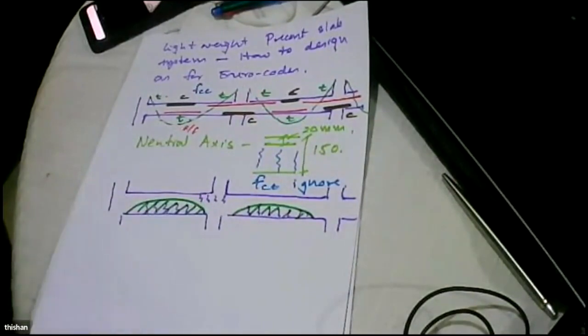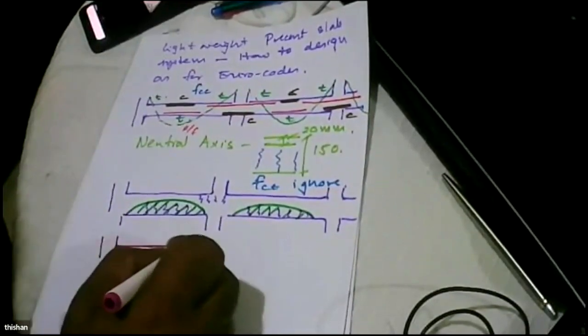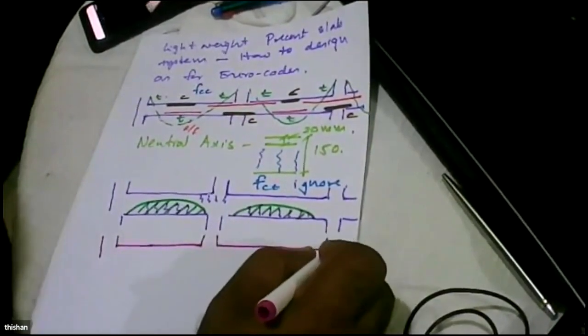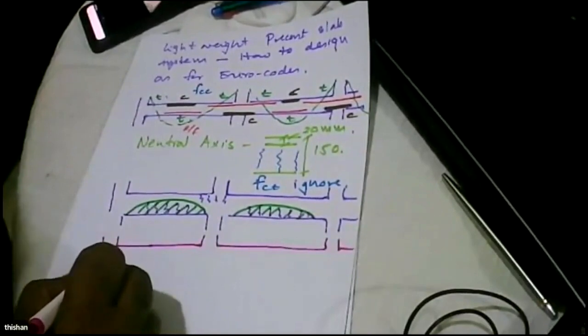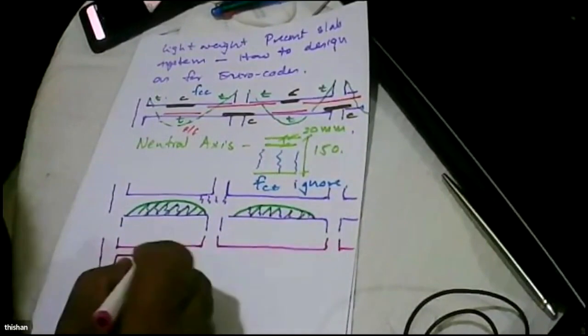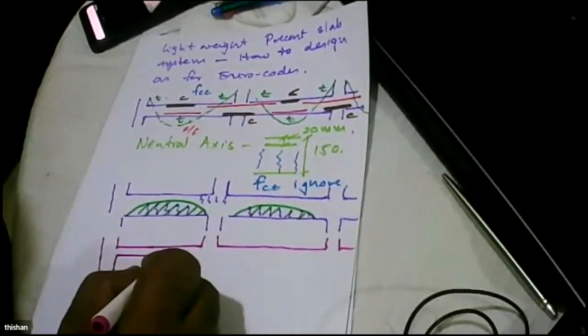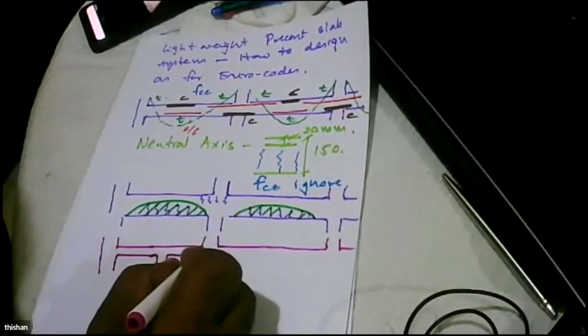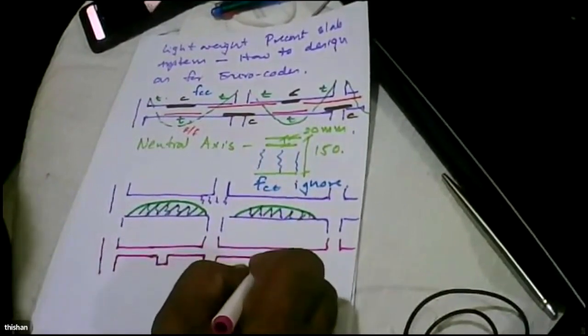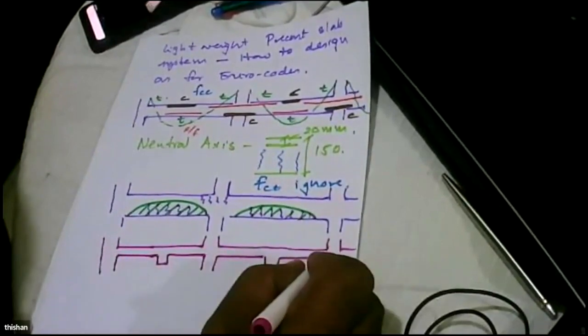So we thought, okay, look at it this way. Now we are going to have a slab. The top surface is intact, and that's the important surface for us. This surface, let's make it thin. But if it's thin, it's going to sag, so put a beam. Here again it's going to sag because now it's thin, so put a beam.